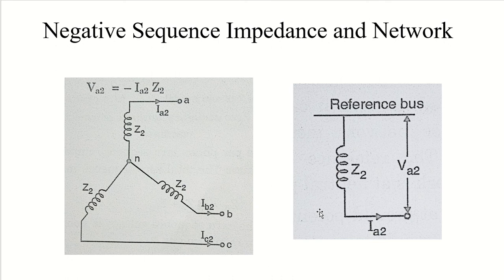So here, what will happen when the synchronous machine has a negative sequence is that it will induce some voltage, and the flow of this negative sequence current in my stator will produce armature reaction in the field, right? So it will rotate in the opposite direction, not just any opposite direction, but opposite compared to the positive sequence field. With respect to the rotor, its speed will be double the synchronous speed.